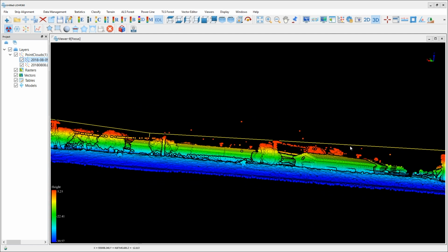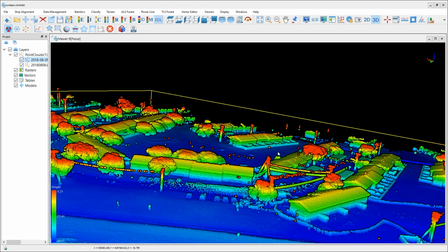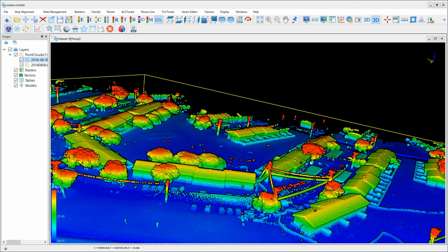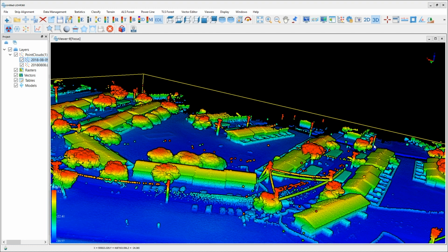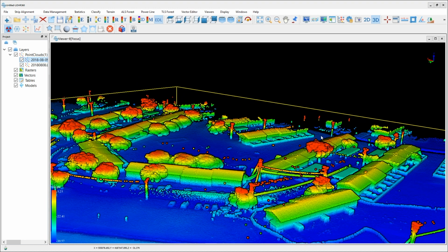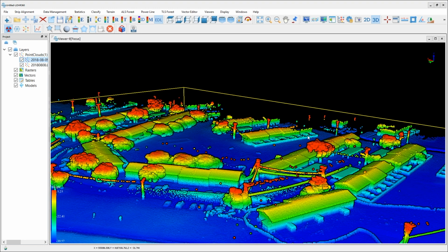I also want to remove some of the anomalies that are created, or I should say non-target data, by people walking around the scene while the live backpack data was created. I'll do this also using the classification tool to manually identify points representing people, assign them into a class, and then drop them out. This step will be skipped here in this video.